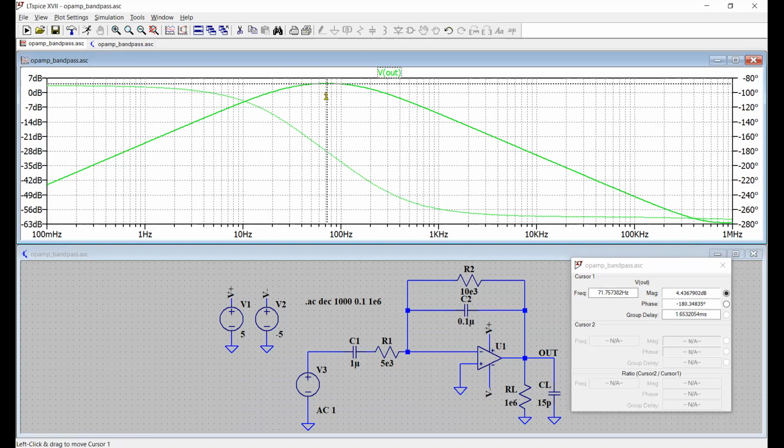The pole frequency at omega C1 is about 1.46, so minus 3 dB less, at about 23 hertz, and the second pole frequency would be at about 200 hertz right over here. And in that case, we have these phase shifts. So the total phase shift matches what we calculated in the theory.